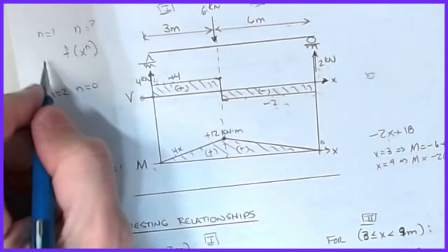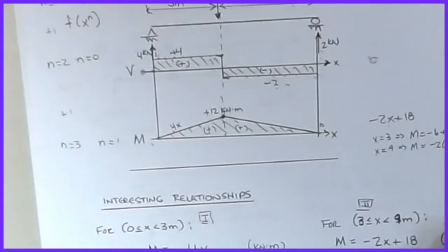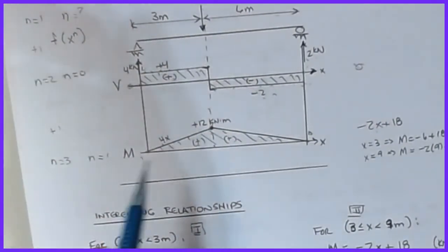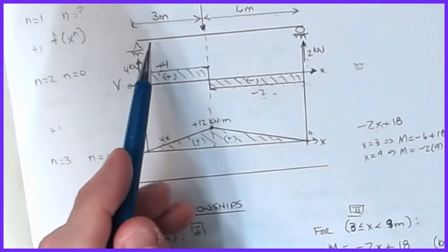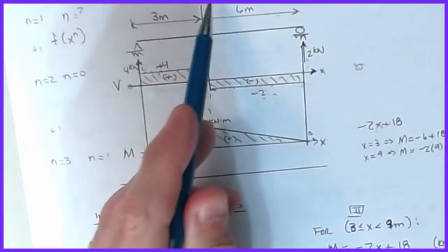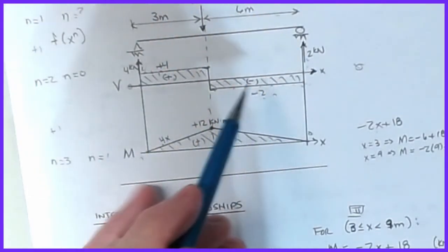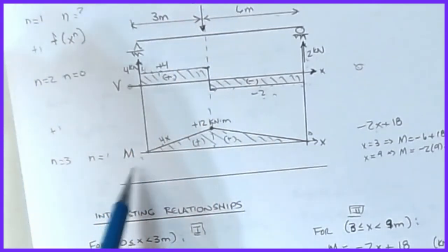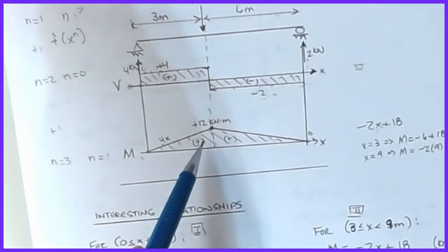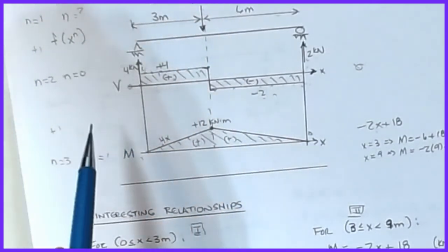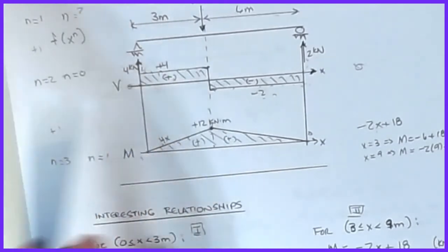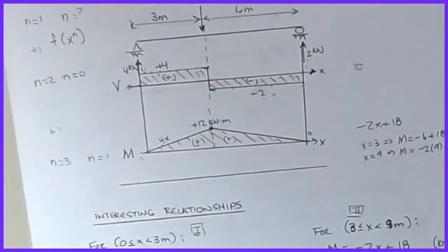It's a plus 1 between each of these diagrams. That's one of the reasons that when we do shear moment diagrams, we always start with the actual structure with the load on it, then I draw the shear diagram next, and then the moment diagram next. I can't do the moment diagram without knowing the shear diagram, as we'll see when we show the other methods that we're going to do.